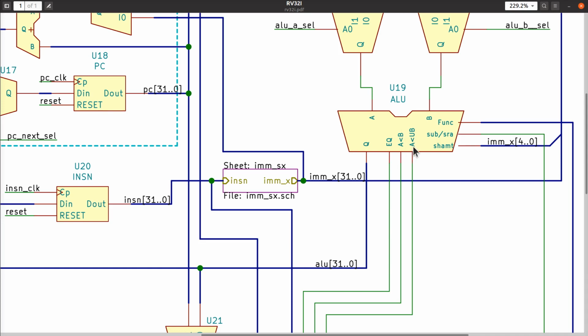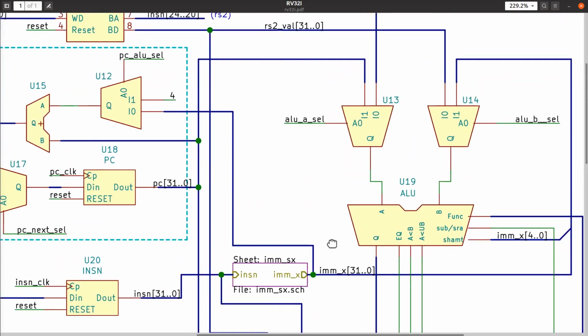Similarly, if A is less than B and the two operands are unsigned values, this one's a little bit easier since they're always positive. So you simply ask if you ended up with an unsigned overflow as a result of subtracting B from A. And when that happens, you know that A had to be less than B, okay? These are all just little logic puzzles that can be solved with truth tables and some combinational circuits, okay?